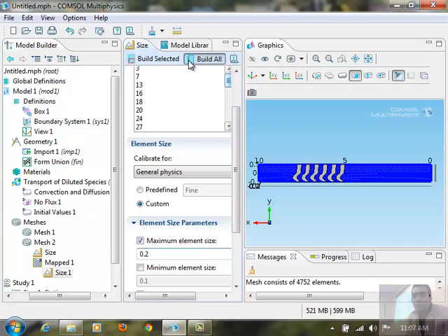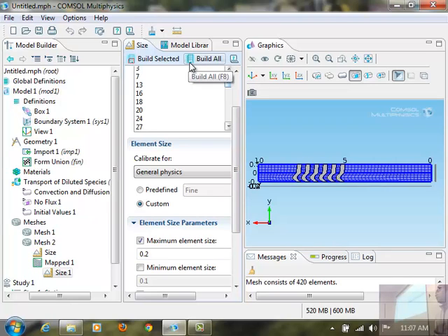So did it select all those areas or boundaries of the group also? Because in this projection you don't see it. No, but it has selected. Yeah, it has selected everything. So now it has selected the full bottom rectangular face, including the faces which intersect with the group boundary. Right, but they are not separate faces. It's just treated as one face. Yes. And now you can sweep it upwards to the top rectangular face.